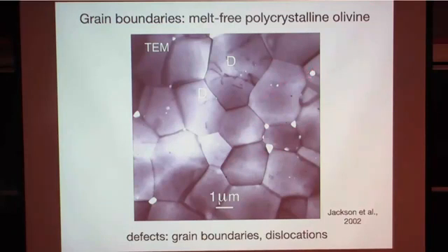There's some pores in the interior. You can see the pores in the interior are smaller, so they got trapped early on during grain growth. The larger ones remain on the grain boundary. But because the pores are not homogeneously distributed, we think they're not contributing. We have no evidence that the pores contribute in any way to what we're measuring, and that's the key difference to melt. Melt, because of the surface energy argument, affects every 3-grain edge and some grain boundaries, whereas the pores are just random and they're not interconnected.